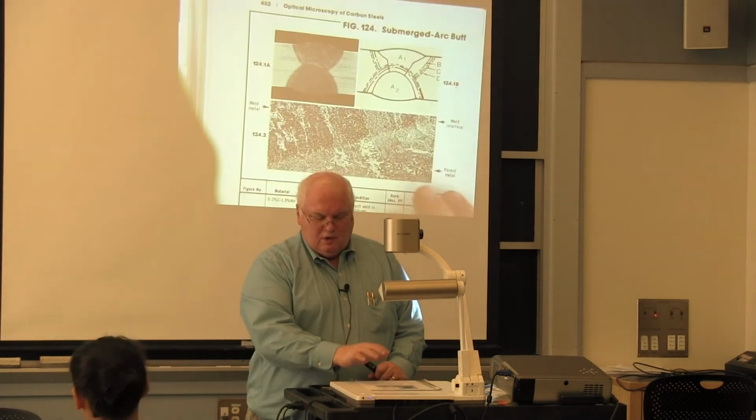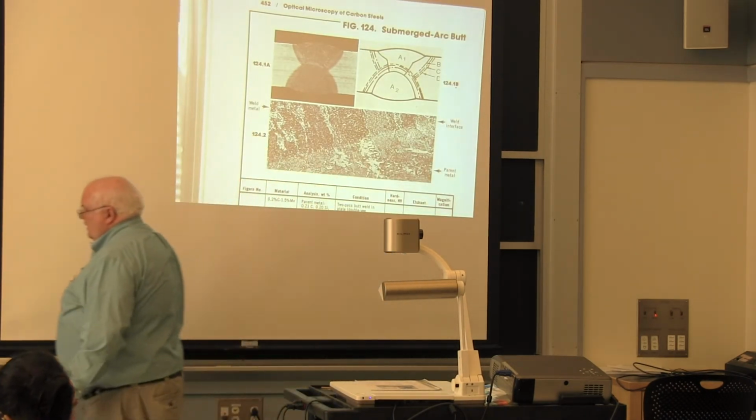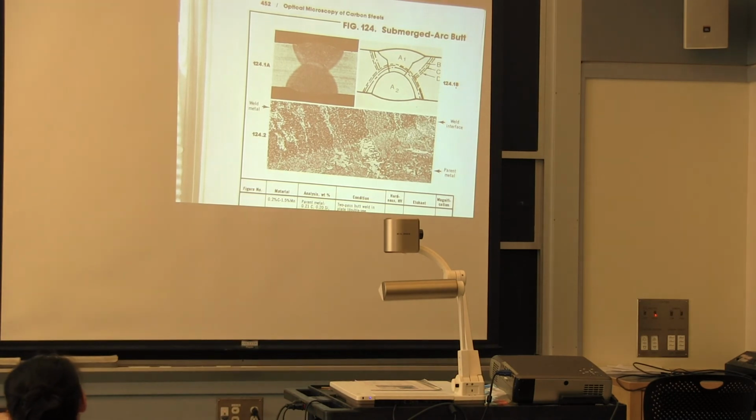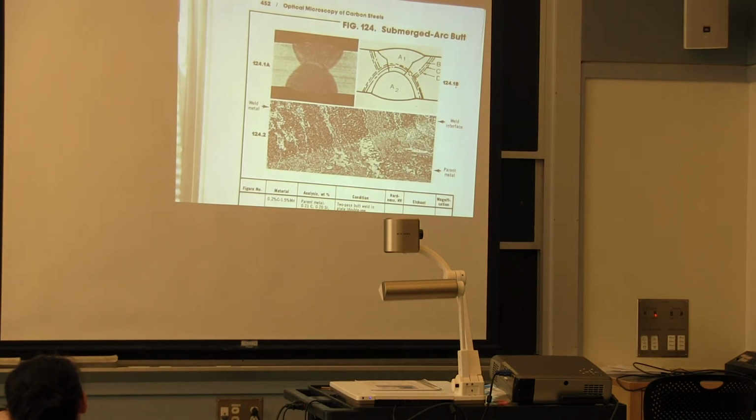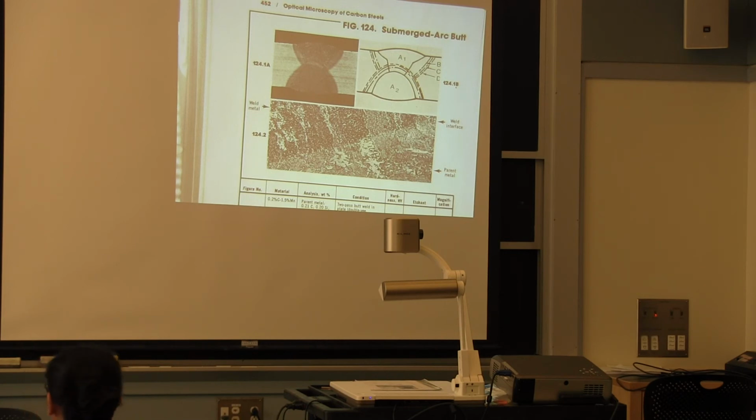Anyway, with the weld metal, you get martensite, and you try to keep your hardness in your weld metal below Rockwell C30. And the petroleum guys like to keep it below Rockwell C22, but they can't use the higher strength. It turns out the bridge guys, when you're building a bridge, we can use steels up to 100 KSI, but we don't use steels any stronger than that because you'd have to do post-weld heat treatment. You can't post-weld heat treat a bridge, not economically anyway.